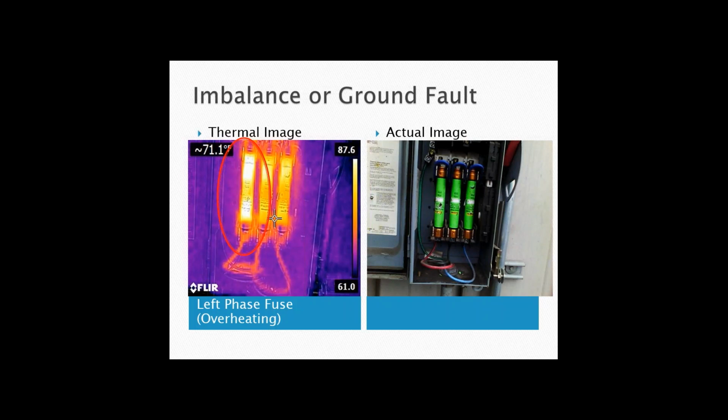I performed a current and balance test, and that test proved to be everything was in band, within 10% as I expected. Well, when I did the megohm test and tested each cable to ground, I determined that that left phase that kept blowing had a really low resistance to ground. And apparently, once the equipment started up and got in service and got to steady state, it would eventually work its way to ground and blow that left phase. So this is a way to use that instrument.